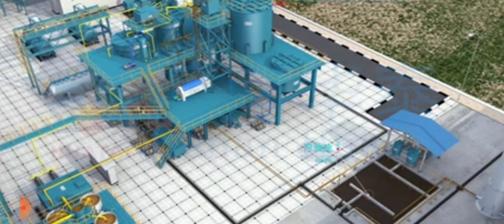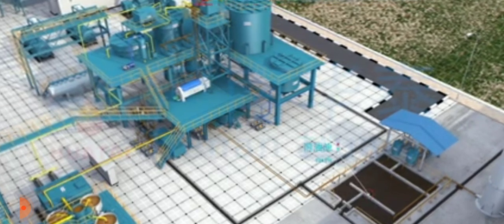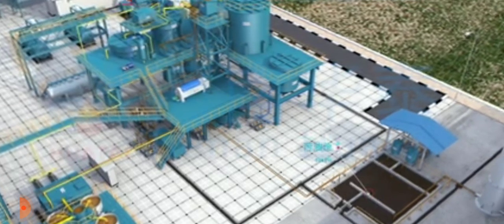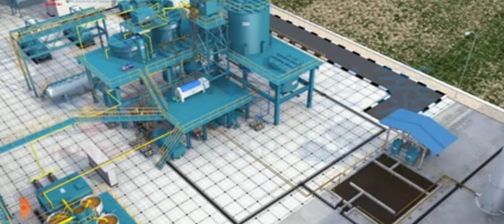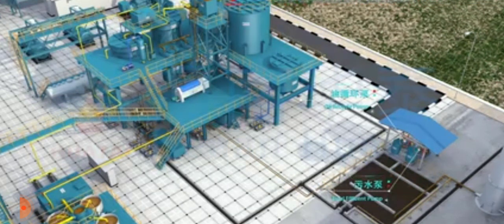The fat pit collects all dirty oil and water in the production plant and separates them into dirty oil and water. Dirty oil is conveyed to the crude oil tank by the oil circulation pump. Dirty water is conveyed to the dirty oil pit by the effluent pump.